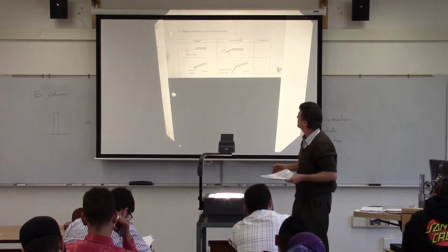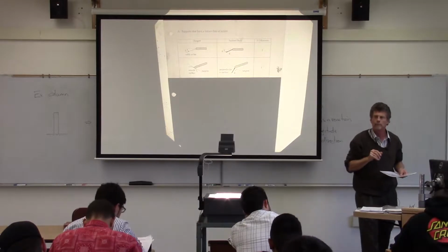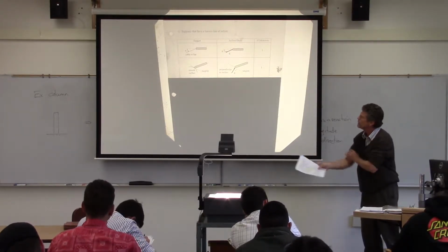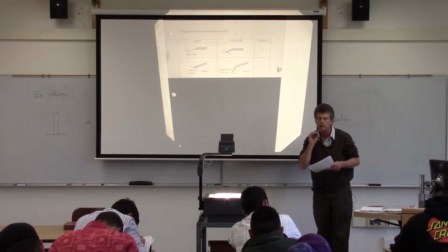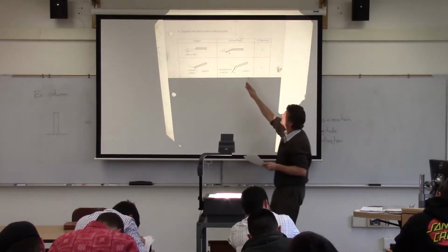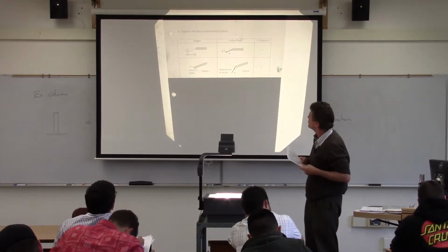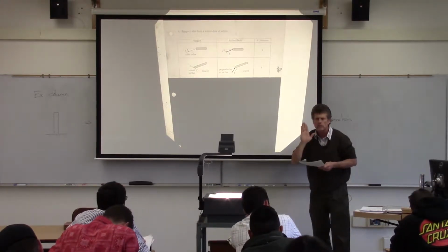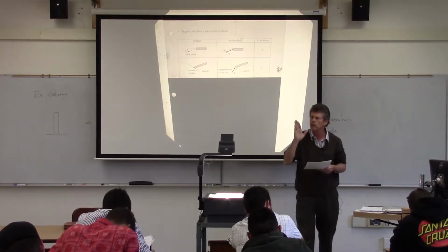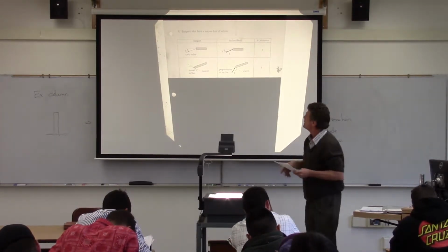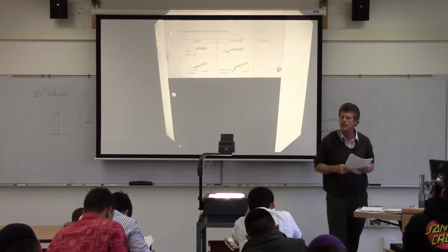Now the next thing is some sort of a smooth surface. And now I don't even have a flat surface there. But going back to your comment on normal, again, think about what motions are being impeded here by that surface. Well, the surface is going to say you can't come through me. I'm a hard surface. I might be made out of marble or something like that, or concrete. We're going to remove that surface, but basically we're going to substitute a force that's going to be perpendicular to the tangent of the surface at that point.